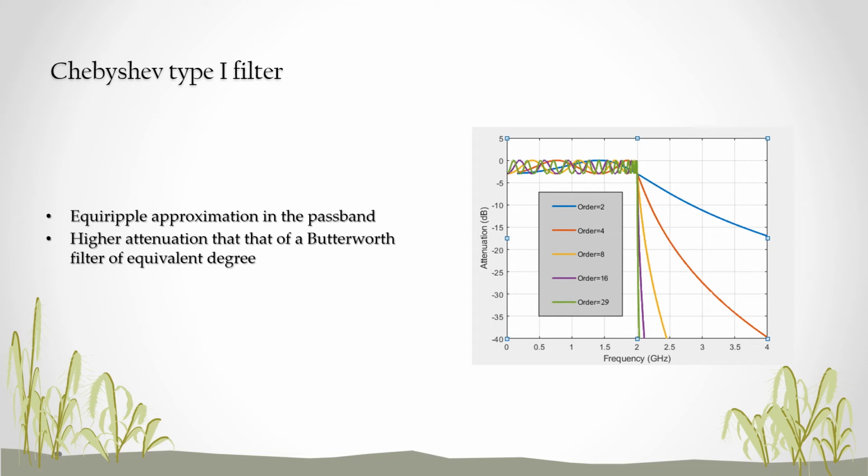It should be noted that increasing the order of the filter decreases the width of the transition band, but then a signal with a higher number of ripples in the passband occurs. The number of ripples in the passband determines the filter order. For the Chebyshev type 1 filter, the amplitude characteristic varies between two tolerance limits, i.e., the error oscillates with an equal peak over the amplitude response in the passband. The cutoff frequency remains the same as with the Butterworth filter, 2 GHz.